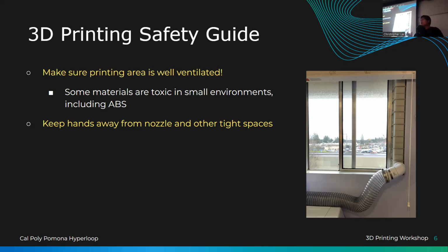Because you don't want it falling off mid-print. So you want it to be hot when you're tightening it, because when it's hot, metal expands. And when it expands, it allows you to push it in further than when it's cold. So that's just my 2 cents on nozzles.